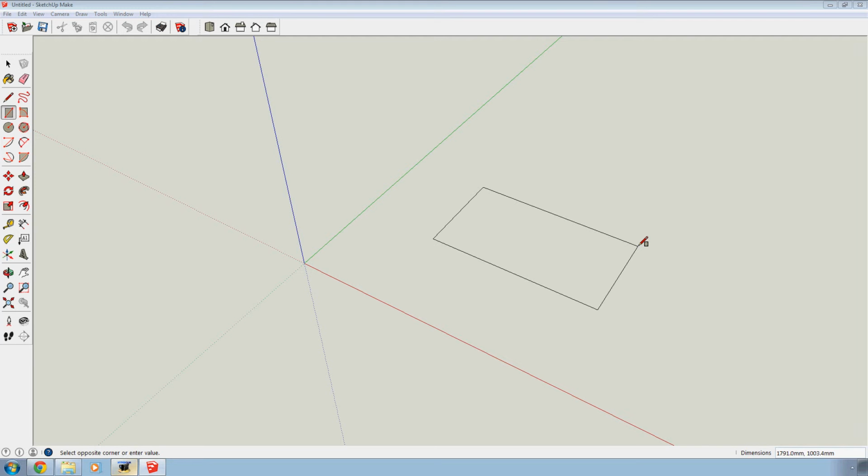So I've decided I'm going to draw a standard unit. It's going to be 600 wide and we'll say 590 deep. So 600, 590. Press enter. You'll see the rectangle shrink down to the size that we actually wanted. It's always useful when you're drawing things to draw it exaggerated in some way, and then when you enter the actual dimensions you'll see the actual movement take place, and you'll know that you have actually successfully made the movement that you wanted to make.